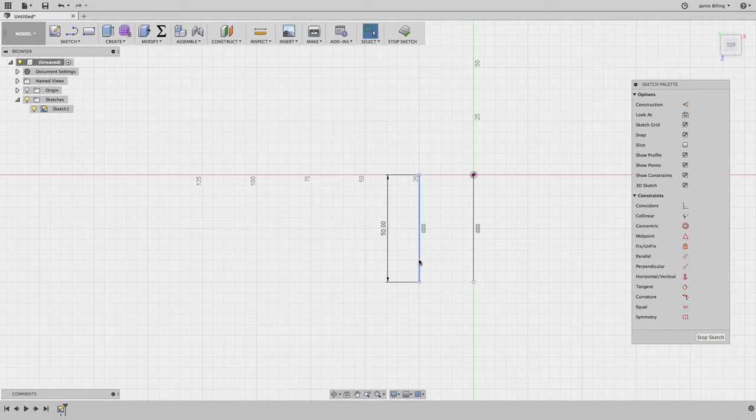Using the Line tool, we can also sketch multiple lines in succession. Press L on the keyboard to activate the Line tool. Now click 5 points to create 4 lines at any angle and any length. Then click the green tick to confirm the lines. We could have sketched those 4 lines, setting the lengths and angles using the keyboard and our tab keys.